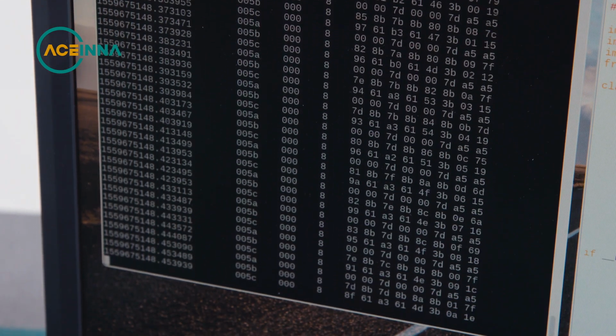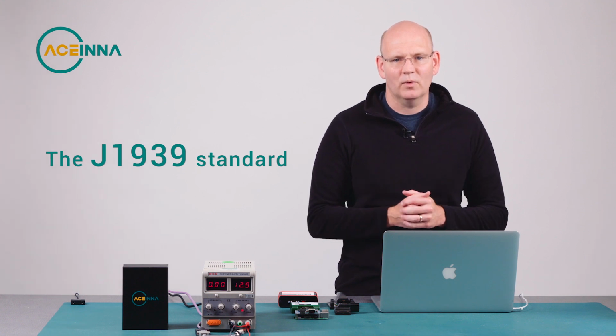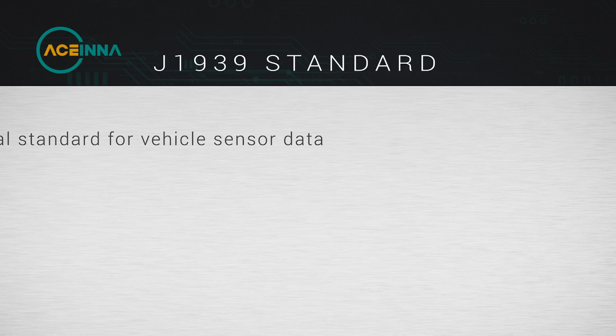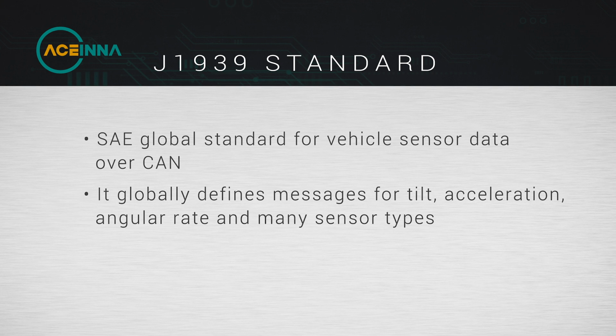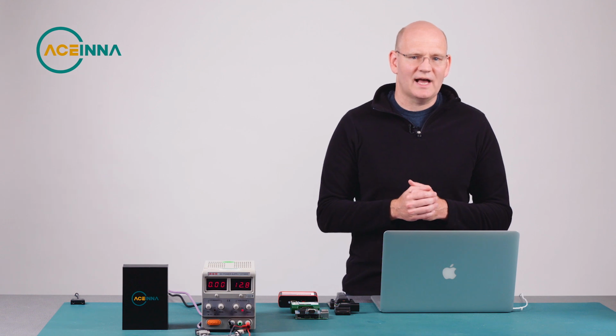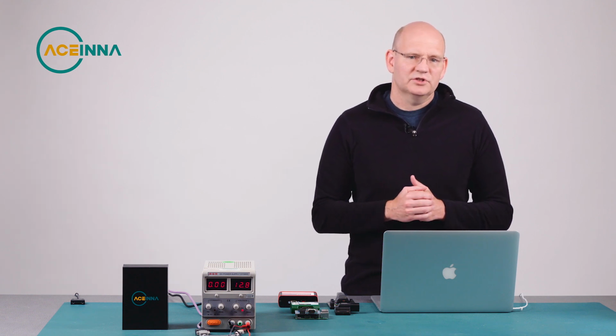Now let's consider the J1939 standard, what it's for, and why it's an even better way to share data over the CAN bus. J1939 is an SAE global standard for vehicle sensor data over CAN. It globally defines messages for tilt, acceleration, angular rate, and many other sensor types. If we implement J1939, then everyone knows exactly how your messages are formatted and work.